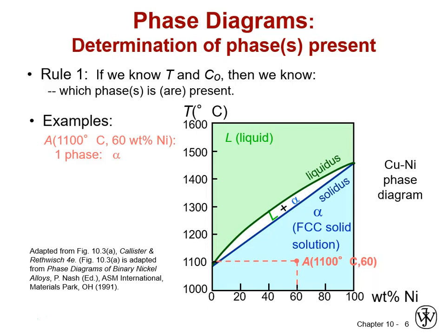If we cool quickly and we have a nickel-rich grain center and a copper-rich grain boundary, even if you have an average 35 weight percent overall material, which you would predict to start melting somewhere just shy of 1200 degrees, if you had a copper-rich grain boundary, it might start melting just a little above 1100.